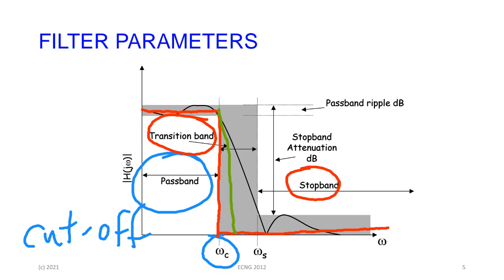And then how it behaves in each band is also an issue. Some filters have what is known as a pass band ripple. So inside the pass band itself, it's passing the signal, but it has some little ripple. And then it stops. And in the stop band, it doesn't simply switch off, but it also has a little ripple inside there. So it's bouncing up and down in the pass band and also in the stop band as well.